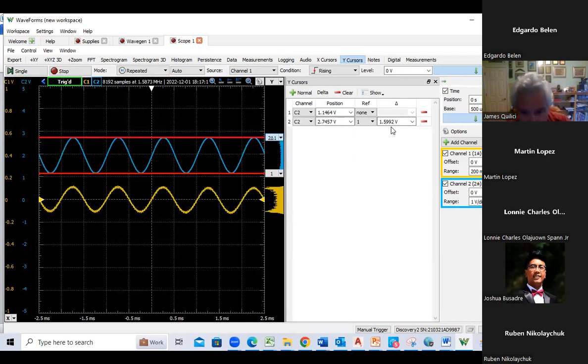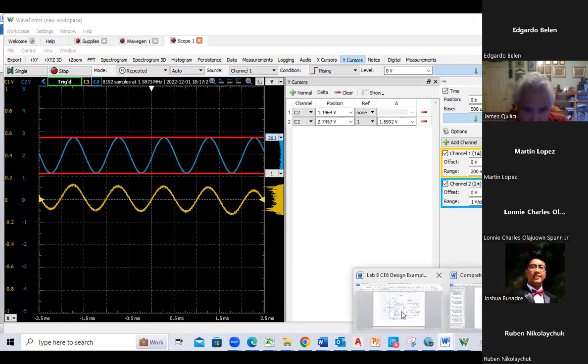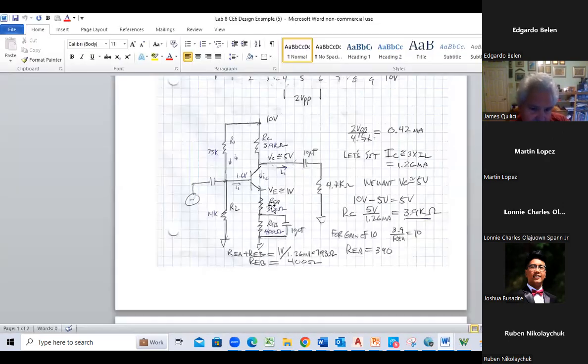Okay, so on my circuit, there's 2 ways to work this. I always start by reducing the emitter resistor. And what we saw is when I reduce this, the collector voltage came down too, because essentially there's more current going through here, and so I have a bigger voltage drop across there.